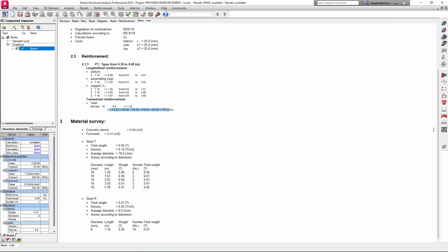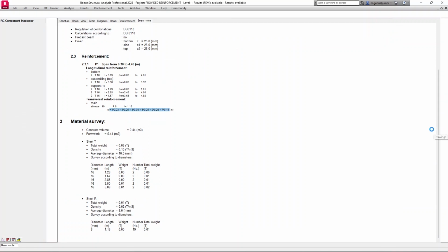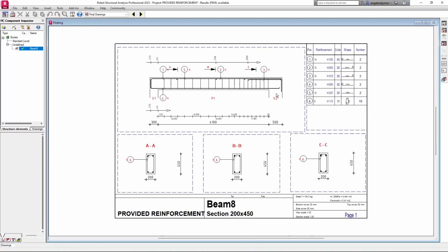Then if I want the drawing, I can go to this option here, click on it. And this is how the drawing looks like. So I think it's only one page. So we have the bending schedule here. Then we have how the links have been distributed, as you can see. So a spacing of 225 before now the links begin. So we have 3 links at 250, then 3 links at 300, 3 at 250, 2 at 200. It goes on like that.